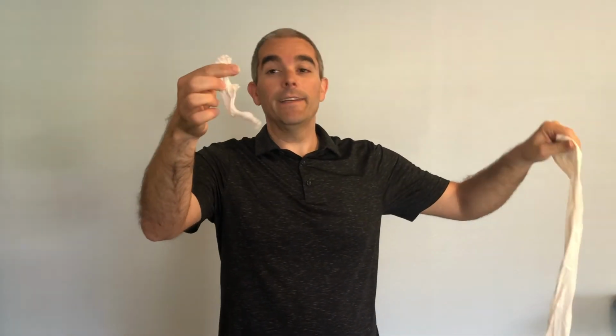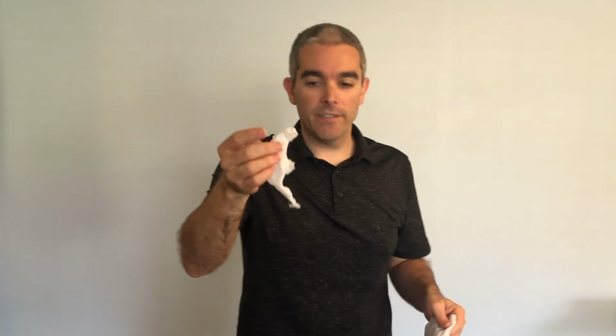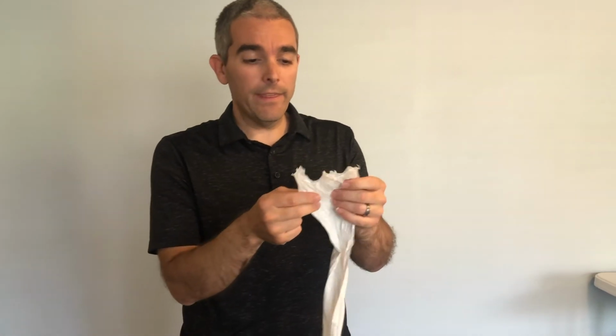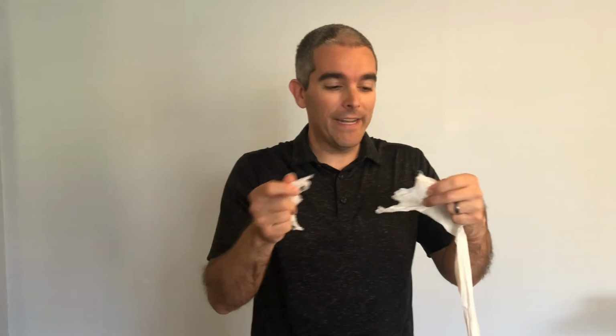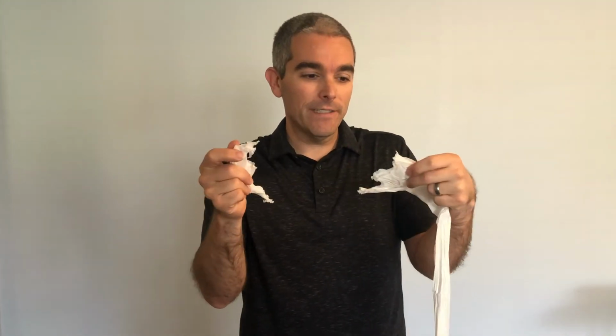As I do this, you see that I pull, you see we get yielding, and then very quickly we end up getting fracture. One of the things about fracture is you have to use what we call the net section. When we come up with our formulas for fracture, we're concerned about fracture because it causes physical separation of the member, and that's pretty dangerous, especially as we're designing a building or something like that. That's pretty bad. So we want to prevent physical separation or permanent separation of our connections. And so that's why we check for fracture, and you want to make sure you use the net section area.